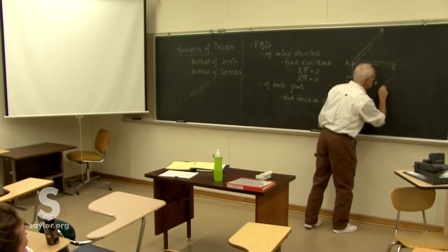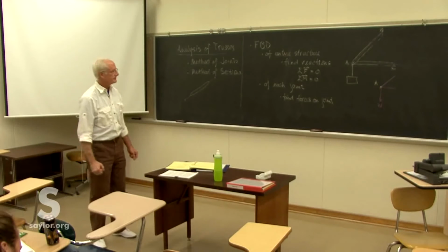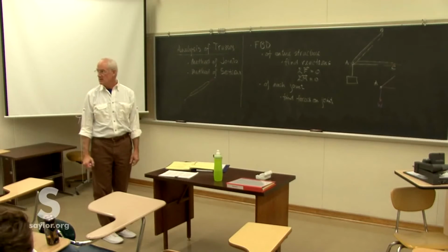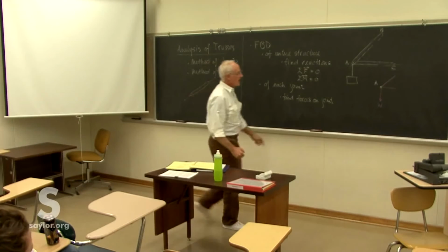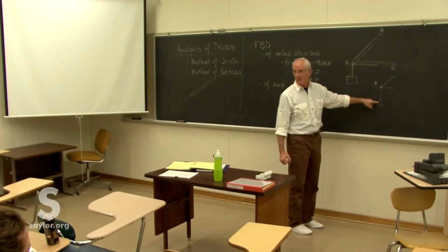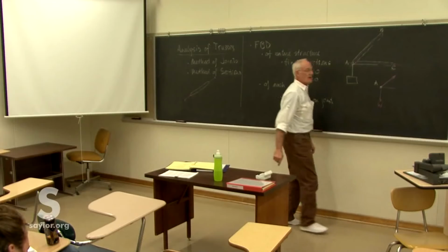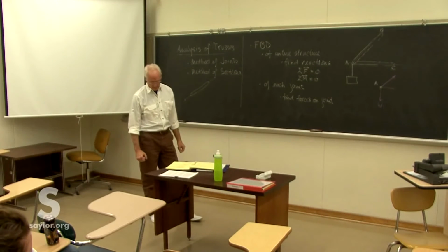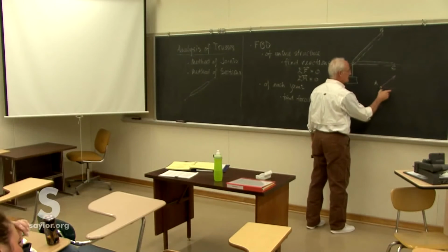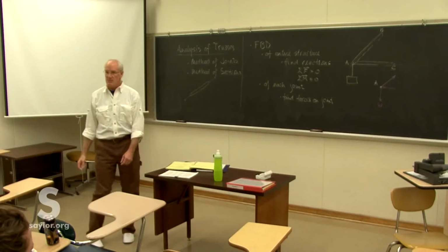And so we have another one that's going to be in that angle, that direction, because that's where the next joint lies. Once we've got that much, we can even determine the general sense of them. If I have no other forces involved, and I've got one down force, I better have some up force. The only other place that could come is here, so I know for a fact that joint must go that way. Since I now have some right pulling force, I need some left pulling force, so I know that joint must go that way. That helps a lot, it just eliminates minus signs.